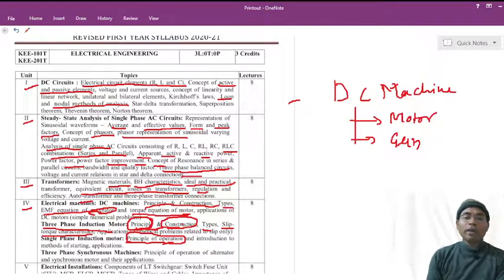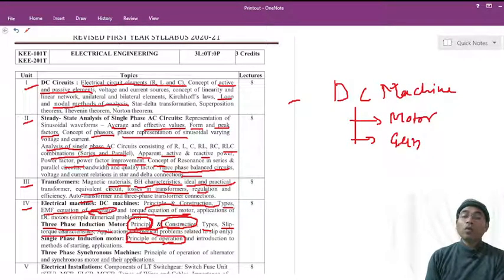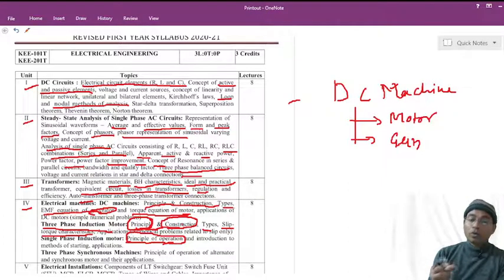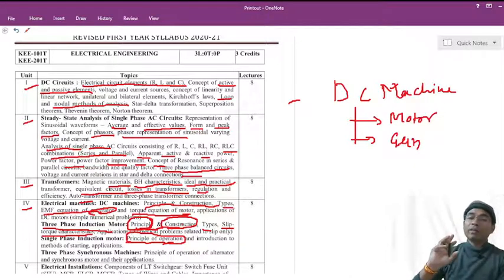So how can you make single phase induction motor self starting? That are the starting methods. So there are many starting methods. As we can see that in our house, the ceiling fan has a condenser connected over the center part. So that condenser actually helps this fan to operate, is used to make it self start. When you switch on the motor with the help of that condenser, this fan gets its initial torque and it starts rotating in a particular direction.